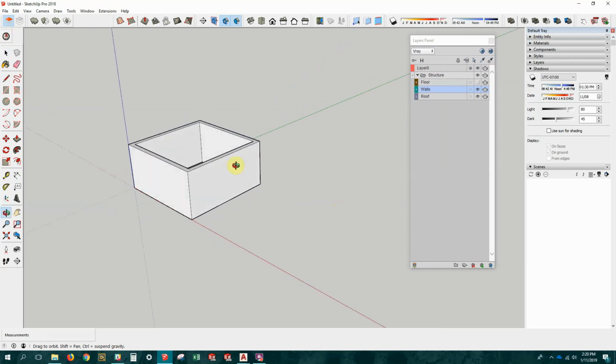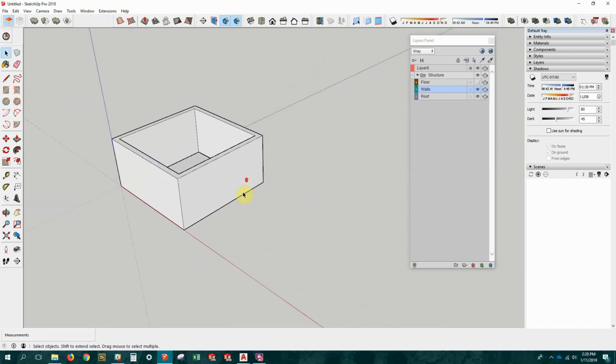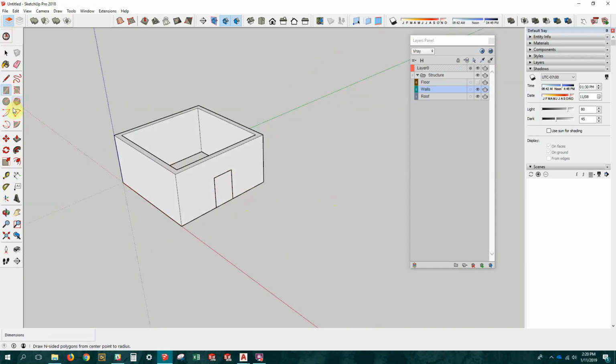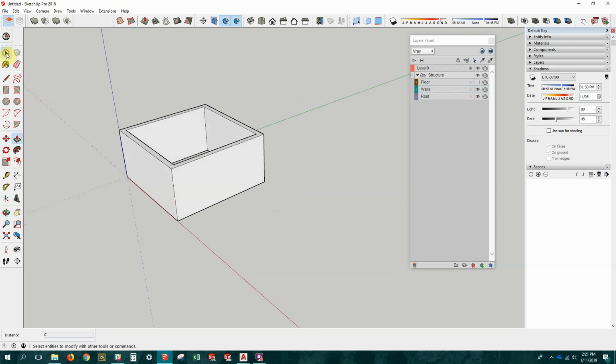So now let's poke some doors in this, or a door and some windows, and let's just first go random. Now remember, if I were to draw a rectangle that I wanted to be a door on this wall and try to punch it out, I won't be able to do that. I can come out, I can go in, but it's not punching anything out. It's a volume. Remember, that's because we are drawing on the group, not in it.